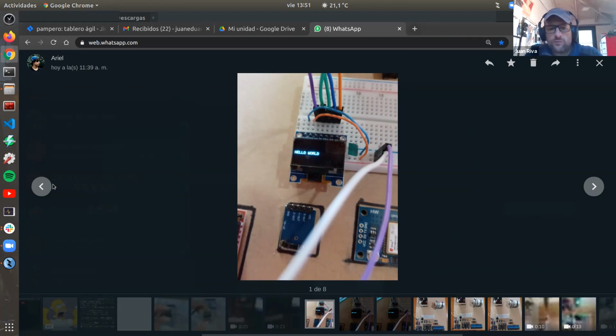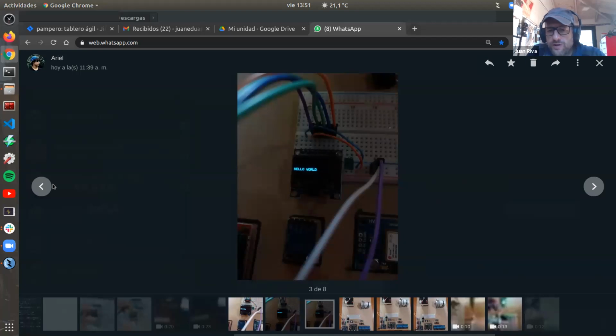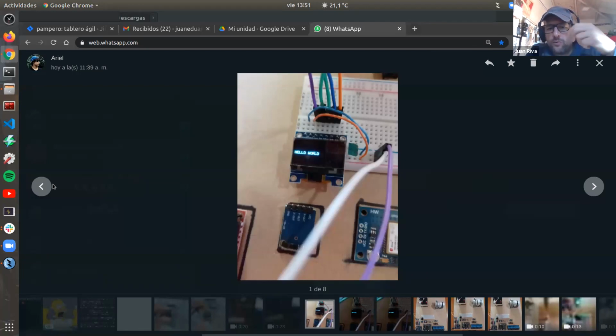Here our approach is I will try to put this OLED little screen. Are you seeing my computer? I see, yes, hello world. Okay, yes. So as we go through the script, we are going to throw messages to that OLED screen saying, now we are using the motor. So if the motor is not moving, or if we are not getting feedback from one of the sensors, we will know that that sensor is having the problem before we put it in the tractor.